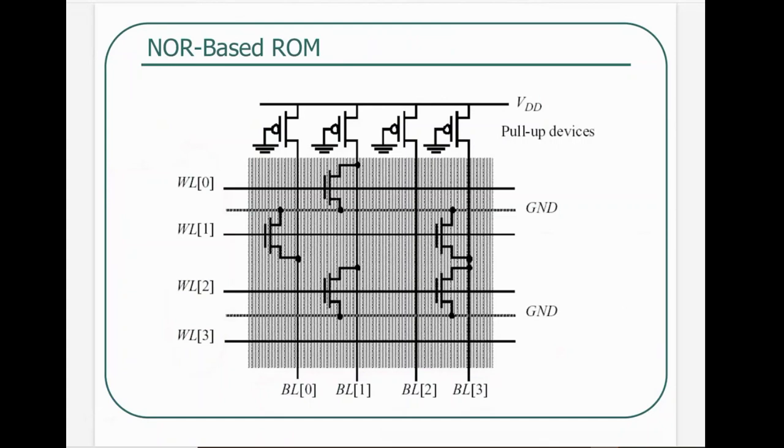When we made a 2-input NOR gate using CMOS transistors, how was the configuration in the pull-down network? Were transistors in parallel? That's right. So NOR is this or this, right? Alternative paths. Of course, that means parallel.